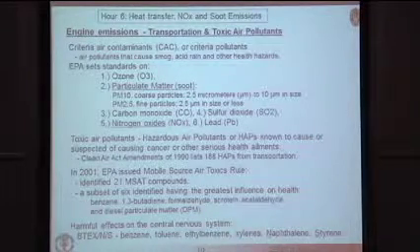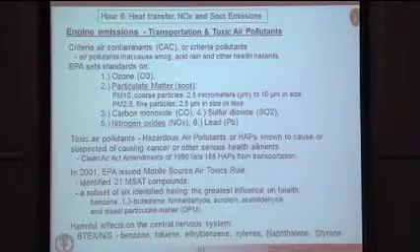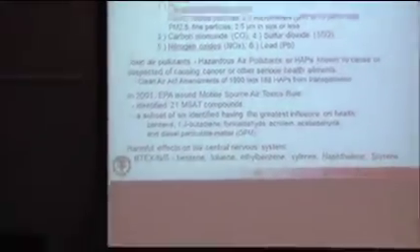So lead we don't have to worry about because they took that out of the fuel. Sulfur we don't have to worry too much about because now sulfur is really at low parts per million in diesel fuels, except when you talk about marine fuels, but for truck engines and so on, sulfur is very low. Particulate and nitric oxide are really the key things for the diesel community.